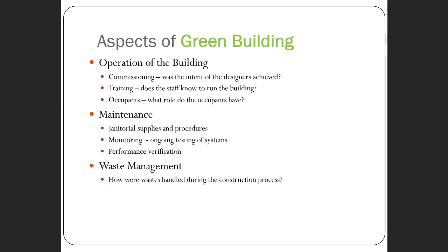Commissioning is a structured process that's typically done at the end of construction to put all the systems in operation and to make sure that the intent of the designers was achieved, right? The architect and the designers designed the building and said it's supposed to work like this. Is it actually doing the things that those designers intended?